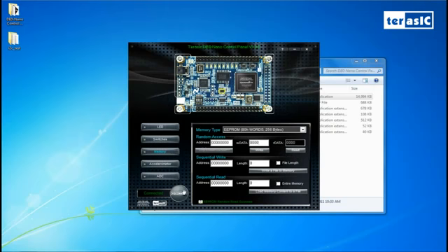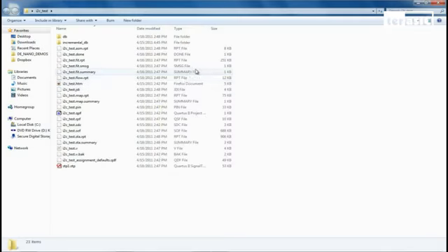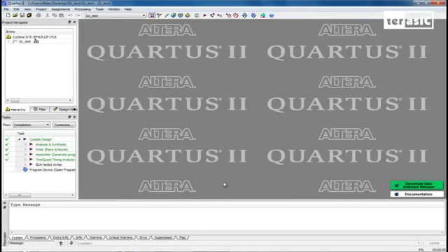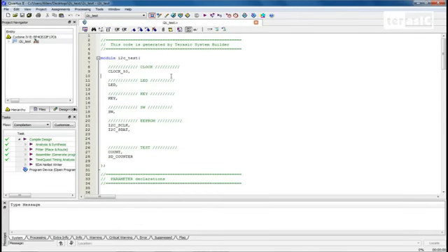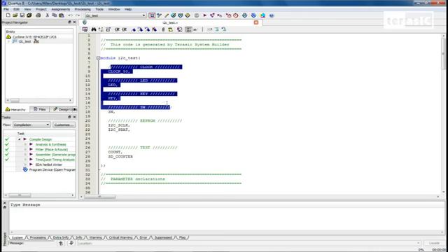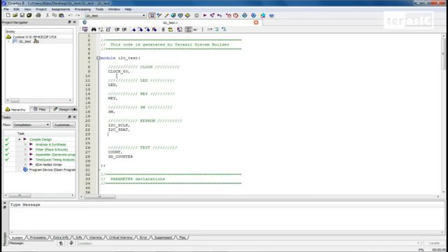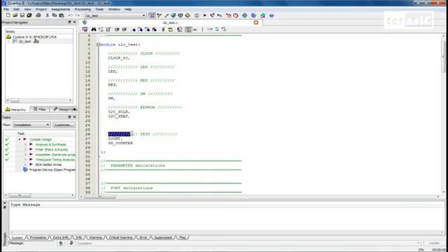So now that's done, we can disconnect our control panel, go to our I2C test, which is a project I've already saved, and open the Quartus project up. Now that Quartus is open, we can look at our top module, and we have our basic pin declarations. One thing to notice is our I2C S-clock pins and our I2C SDAT pins. And for the sake of testing, we've also declared other pins, our count and SD counter. I'll explain this further on.